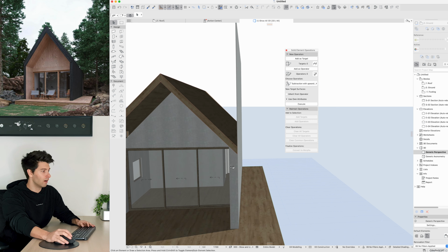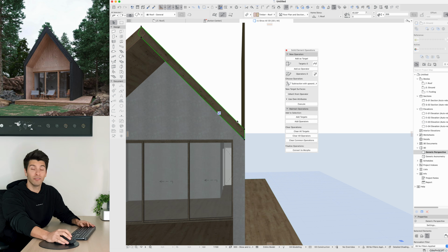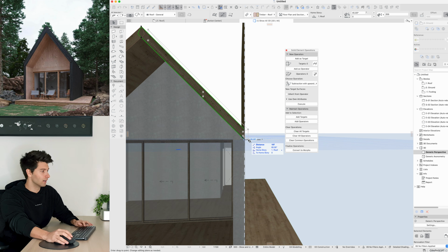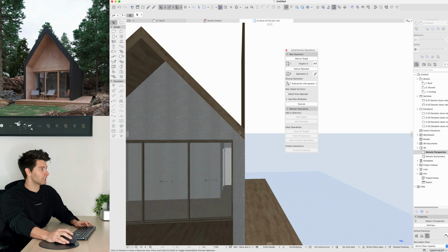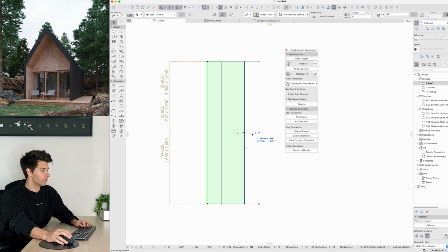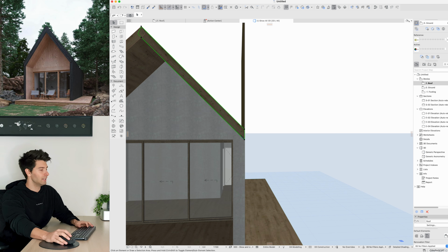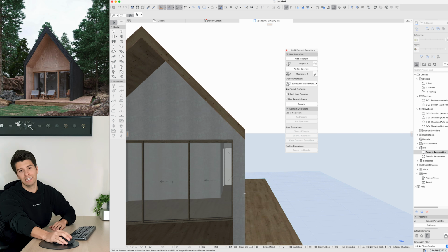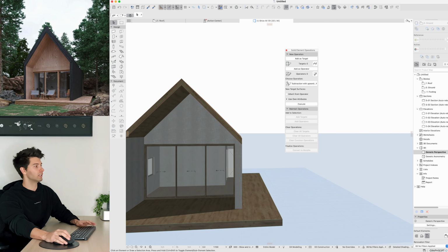What you'll see is a small little error here. Basically, I did not align the edge of my roof perfectly with the edge of my wall, which means I was 10mm out. If I come back to my roof pane, select that roof, adjust that 10mm, and then come back into 3D, we'll see it automatically trims that space perfectly to how we need.